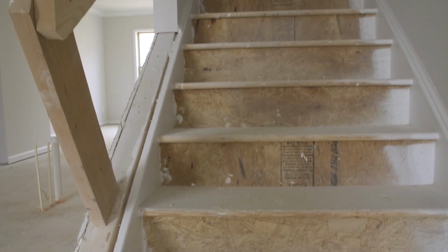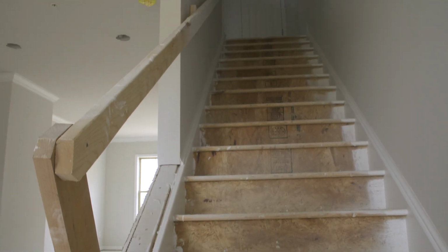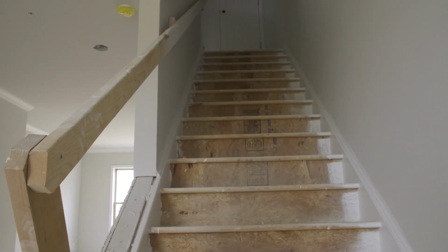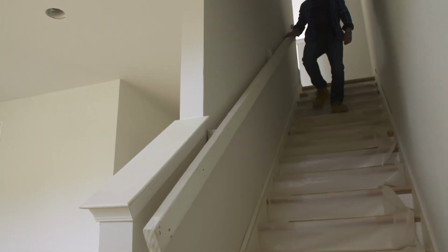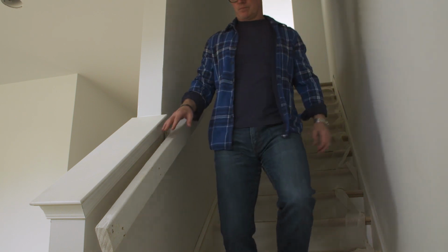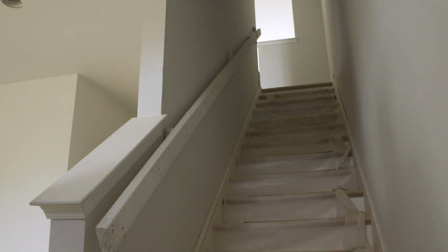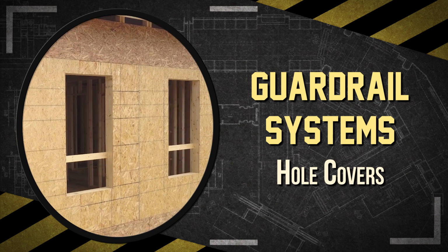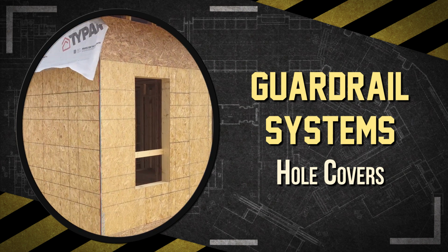The end of your stair rail or handrail must be cut close so as not to create a hazard from projecting ends in walking areas. Finally, if installing a stair rail at the side of any wall, ensure that there is a gap of at least 3 inches to allow for a proper handhold. The essential purpose of guardrails and stair rails is to protect workers from falling to another level.